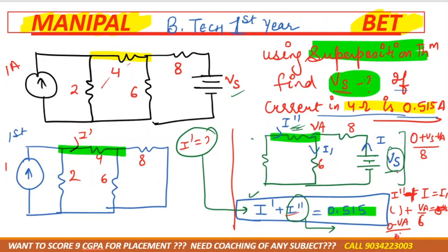So basically in this you will have only a single variable, that is Vs, you can solve it. Okay, how? How much is I double dash? It is moving from 0 to VA, yes or no? Sorry, it is moving away, so it would be minus VA divided by the resistance, that is 2 plus 4, right? 6.